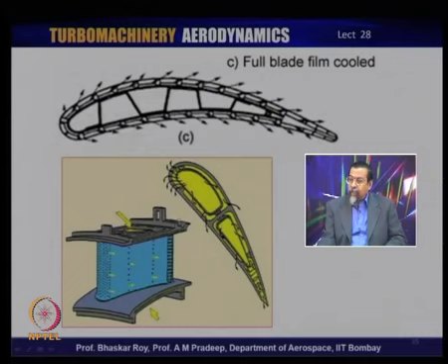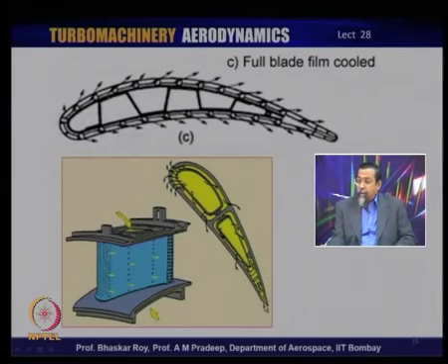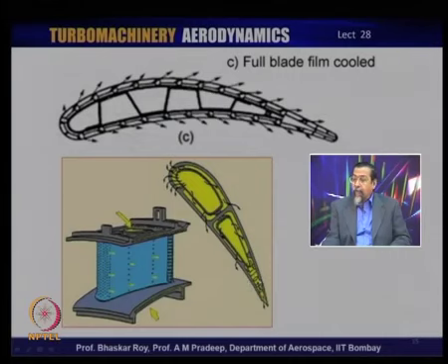On the blade over here, which of course shows a 3-dimensional picture, you have two large internal passages, one passage over here, another passage over here, which of course exits the flow through the trailing edge. Many of the modern turbine trailing edges are indeed not rounded, but truncated like this, or sometimes straight away blunt, to allow this cold air to come out. So, this is something which requires very high manufacturing technology, typical for gas turbine manufacturing. And this is shown over here. You can see the discrete holes that are made over here on the blade surface, which allows this internal air to come out from inside onto the blade surface and create the films on both the surfaces, thereby cooling this area, which we have mentioned many times is an area that gets terribly heated up.